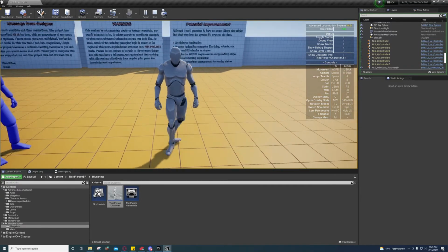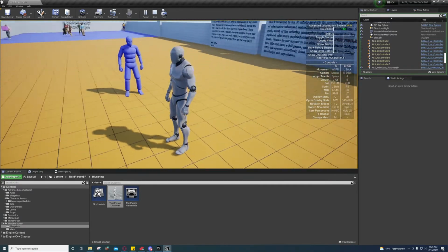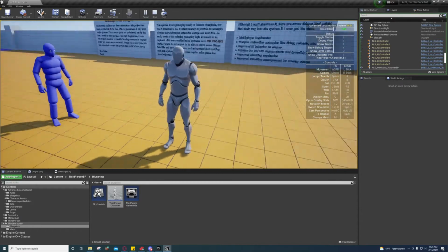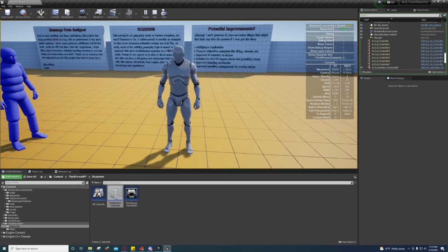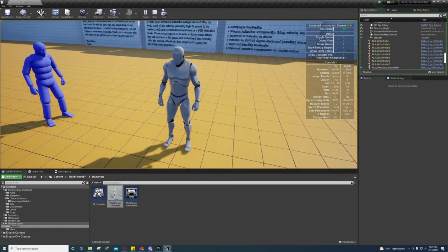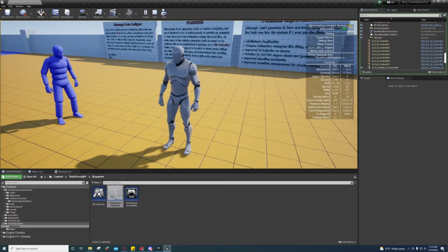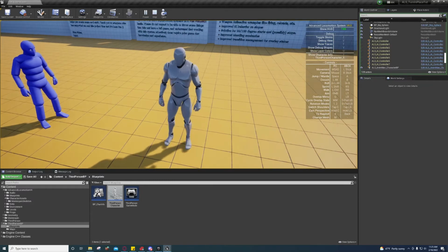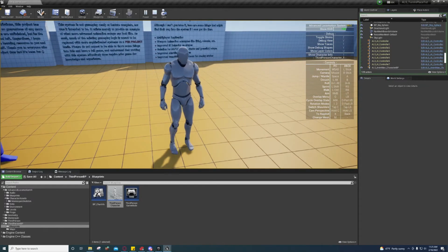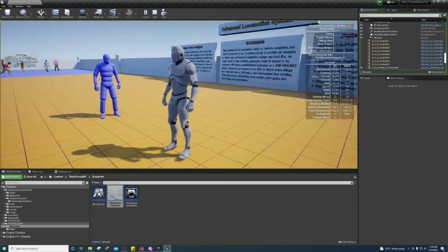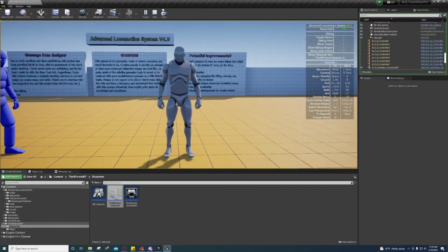And that's what we want right now because we haven't set up the rotation. So we're not using root motion to rotate. We're using values that we calculate. And from my understanding, for the most part, you don't want to use root motion for basic movement like that because it can cause issues when you're trying to do stuff, because I don't think that the rotation is easily translated inside the blueprints.